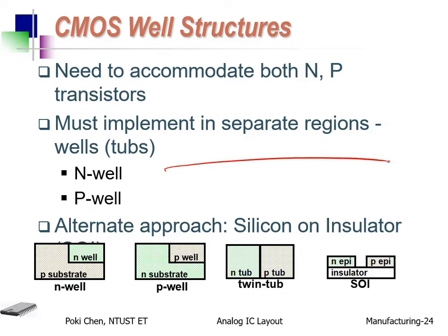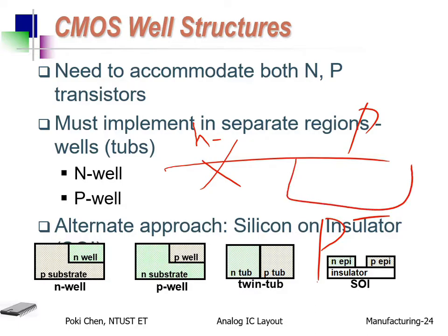On a P-minus substrate, you can fabricate your NMOS directly. Okay? But how about PMOS? No, P on P, we only have enhancement type for major circuits. So you need an N well, then you can fabricate your PMOS. For such a fabrication secret, humankind wasted 20 years. It is a very simple idea, but for fabrication, it's really hard.